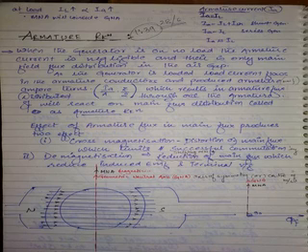In the armature, what are there? Turns are there. Armature is made up of winding turns. Those are conductors basically made into turns. So when current flows in the turns, what is produced? MMF. When MMF is there, immediately it will produce its flux. So where is this flux now? This flux is also on the armature, where the conductors are. If there is a magnet, there is flux on the magnet. If there are conductors carrying current, according to Oersted, around a current carrying conductor there is flux. So there is main flux in the air gap.